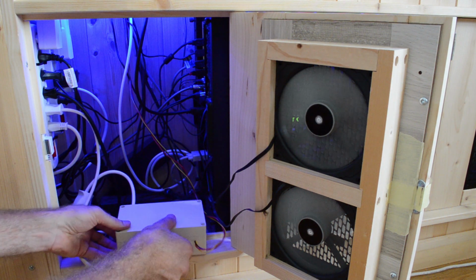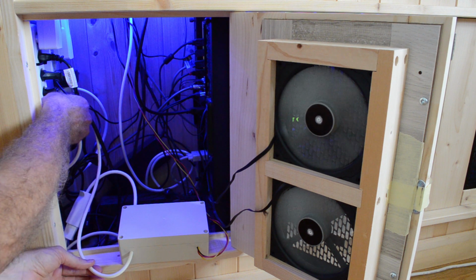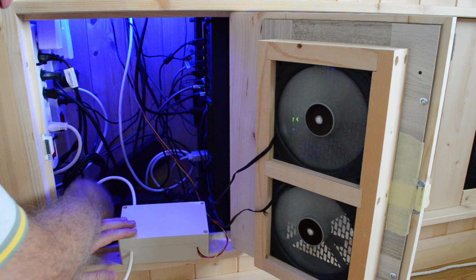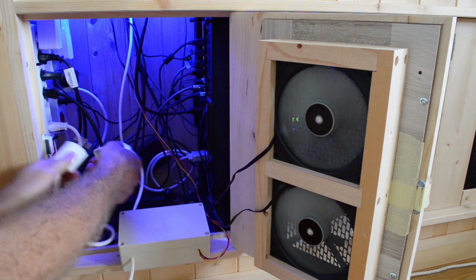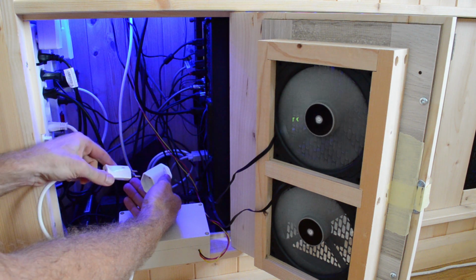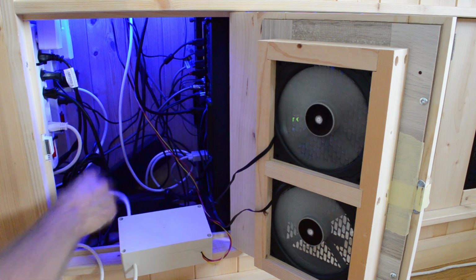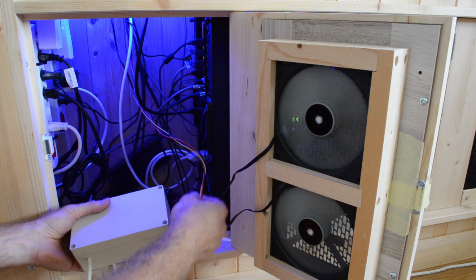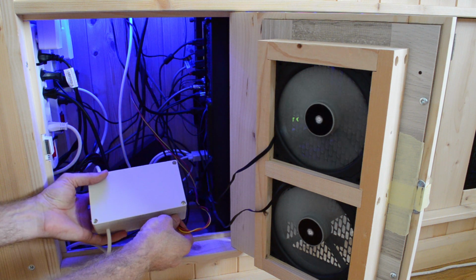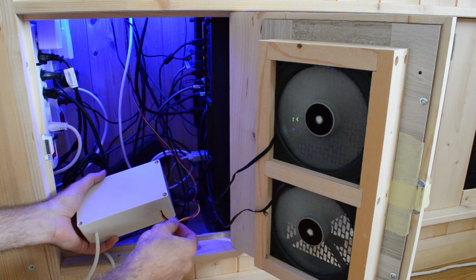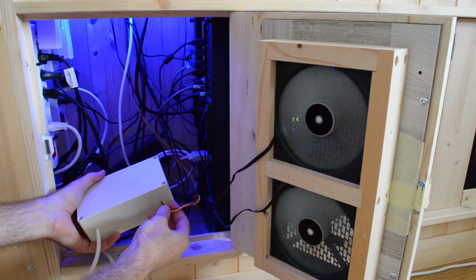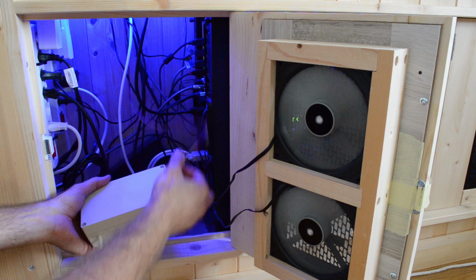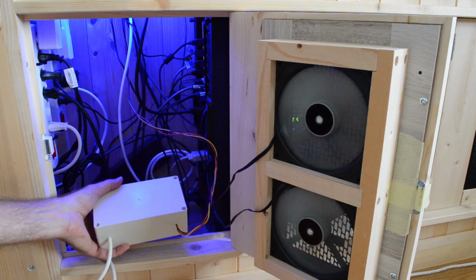But what I've got is, and I'll unplug it right now, this is the 230 volts going into the box, and this is the fan that I've plugged in that I'm controlling inside the box. And here I've got the 5 volt DC coming in to the solid state relay board that you'll see in a second, and then I've got the signal line, so the yellow line, to actually turn on and off the relay. So this comes from the fan controller up in the dashboard.